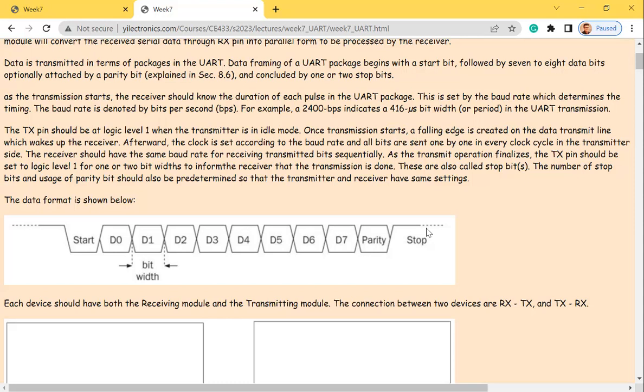I don't know if there are any other types of UART protocols, but for the standard UART, the most traditional UART protocol, it's always 8-bit data. So after 1 byte, it's done. You want to pull it up. So you are signaling the receiver that 1 byte of data has been sent. Be ready for the next one.